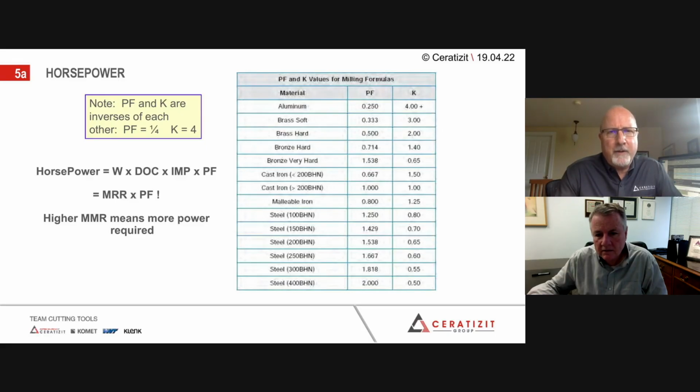But once you round that nose radius, now you're not at 14 degrees anymore, and you cannot high feed past that limit. Otherwise, you'll break all the inserts. So pay close attention to what the max depth of cut is for that particular insert and cutter.